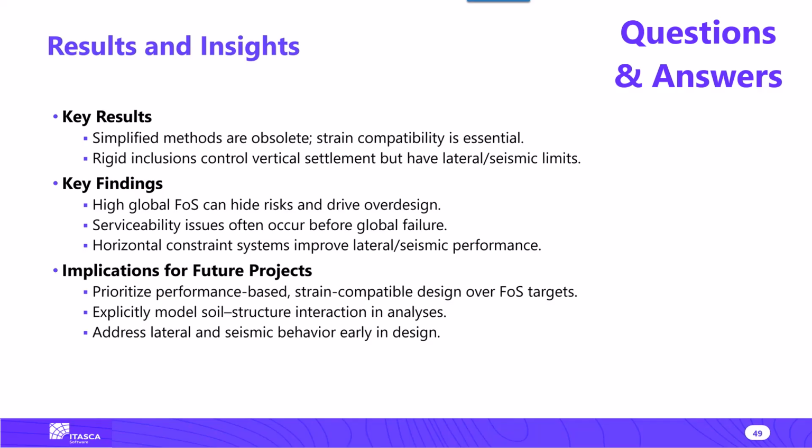For the rigid inclusion, the pile element for a simplified analysis is the best one because it allows me to capture the axial, the shear, and the bending, and somehow you can also set some limit in terms of structural capacity with the three methods that we have shown before. There are other elements, for example, for the walls.